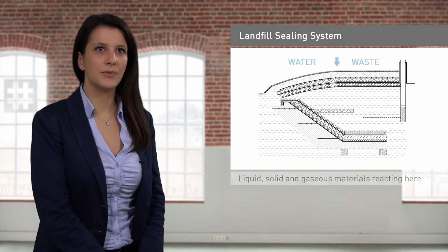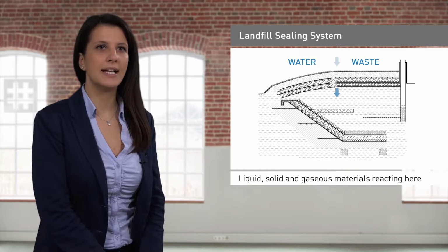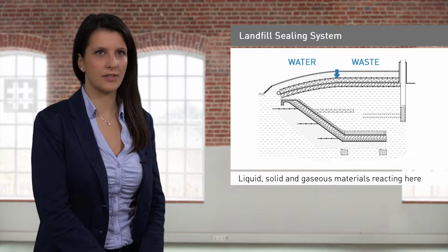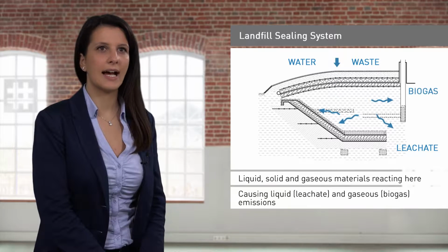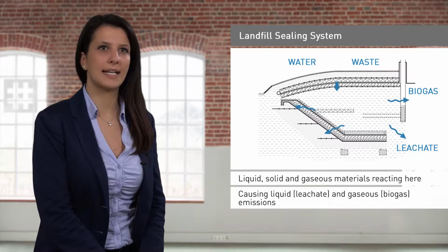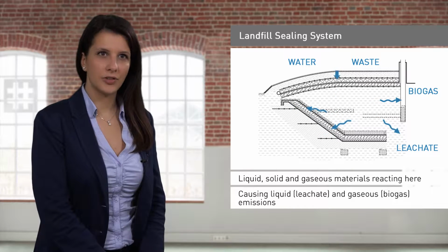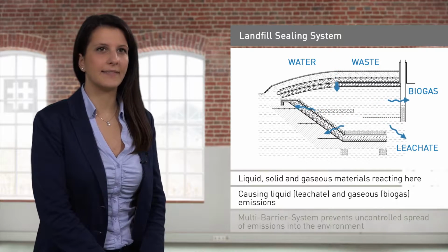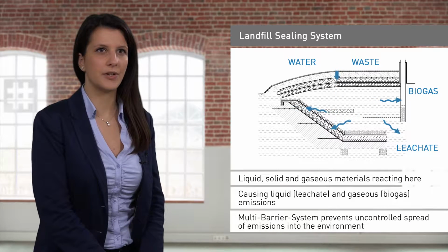The landfill is, for all intents and purposes, a reactor in which liquid, solid and gaseous materials react, causing liquid emissions, leachate, and gaseous emissions, biogas, within a solid matrix, that is, the waste in place, that represents the source of the potential residual emissions. Emission control is typically carried out through the use of a multi-barrier system that prevents the uncontrolled spread of the emissions into the environment.